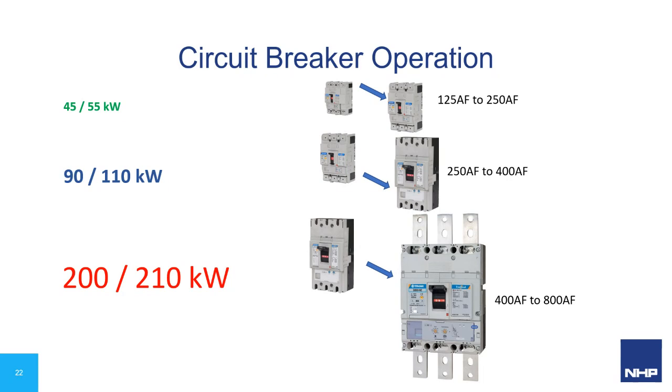Now, the reasons for this we discovered were due to the physical frame size of the circuit breaker being affected by the magnetic effects of the peak inrush of the motor. Increasing any of the settings did nothing to stop the breaker from tripping. For these marginal sizes of motor kilowatt ratings, the only way to prevent a trip was to increase the frame size of the breaker. This had the effect of increasing the total mass of the breaker and the mechanisms to be able to absorb more energy without reacting as though a short circuit event was occurring.